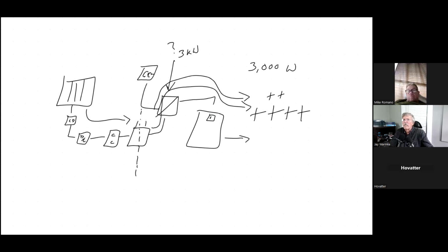What if I put in a 5 kW inverter and I'm at most running 3 kW through that load? No problem. I just bought an inverter bigger than I needed. It works better that way, in fact. You don't want to run at maximum capacity all the time. So this is how you size your array or your inverter in a standalone system.